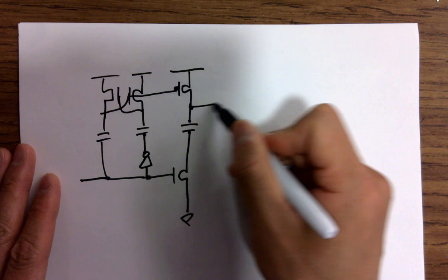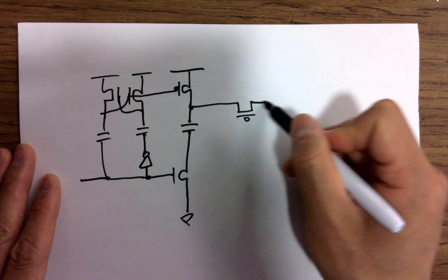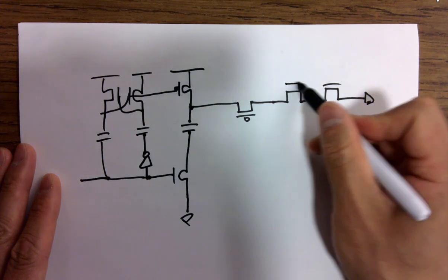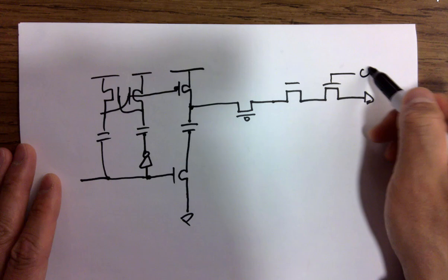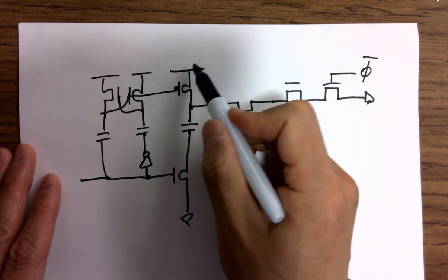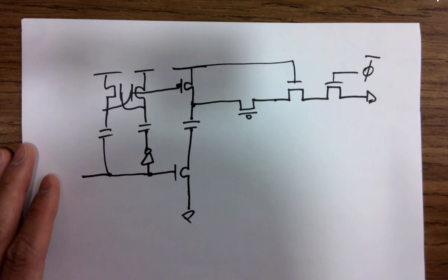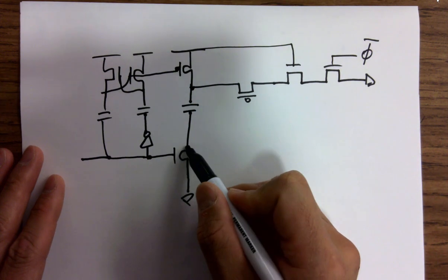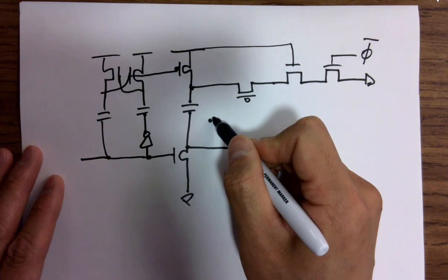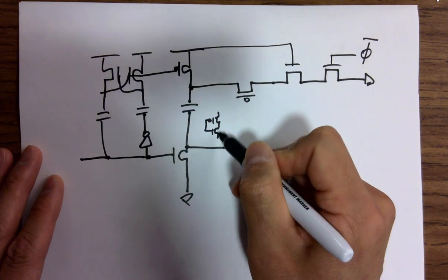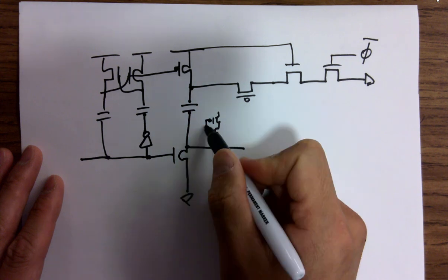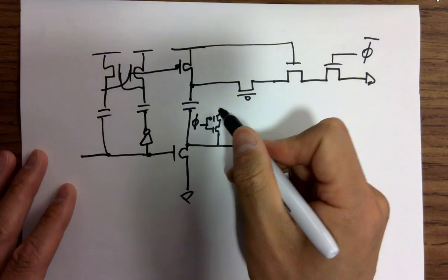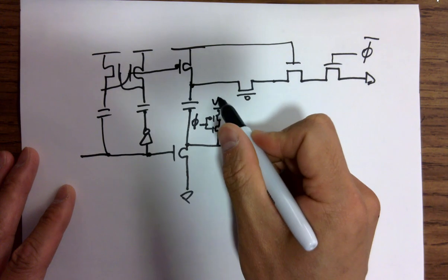And from this point, you got a PMOS. That's a protection NMOS. That's the NMOS to reset. And this one is directly shorted to NMOS to VDD, so it's always open. And for here, we need a little inverter here to pass the signal to the gate of the PMOS, and the signal here is called phi. Okay, and this one goes to VDD.